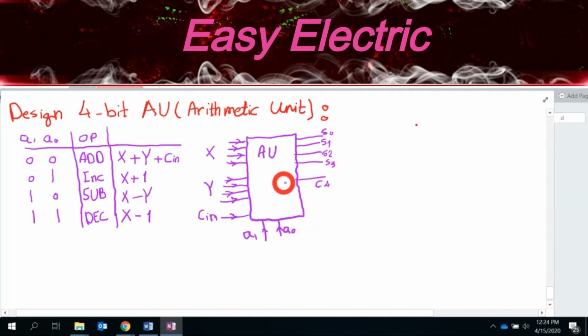So for X minus Y, definitely you need a sign. Because maybe you actually get a negative answer, so I need to have one output which keeps that sign, and X minus 1 is actually the same thing, right? So that means if it's negative, you're able to keep it here. And definitely whenever it is subtraction, you never get the carry, right? You just have the number here, and whether it is positive or negative, you could keep it here, okay? So this is actually the whole story.